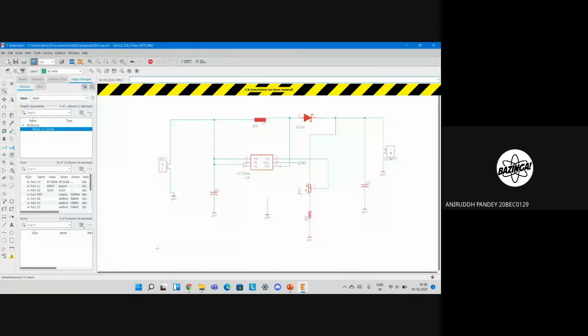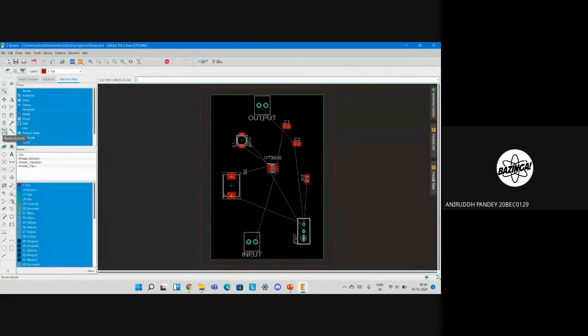I'll open this thing again for routing. Okay, so we are going to manually route all the wires over here. Just go to route. One more thing: whenever making a connection, try not to make a sharp corner, like a 90-degree turn. That is because during the etching process in manufacturing, a 90-degree turn may come out less straight, and less width could come out after etching. So go over here for this option. You'll have 90 degrees as the default, so go for either a 45-degree turn or a smooth curve. Smooth curve is the best, but I'll show with the 45-degree curve.